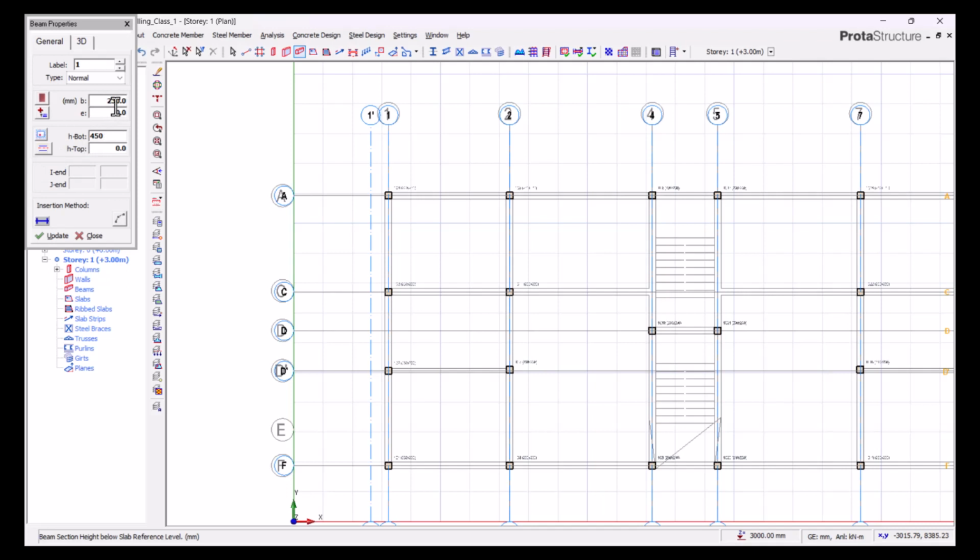as our thickness. And let us also be aware that this might not be the final sizing of whichever member we are creating. This is our preliminary sizing, so after we run the analysis, there may be a need to provide a much thicker or a much wider section. It just depends on the load on this very structure.